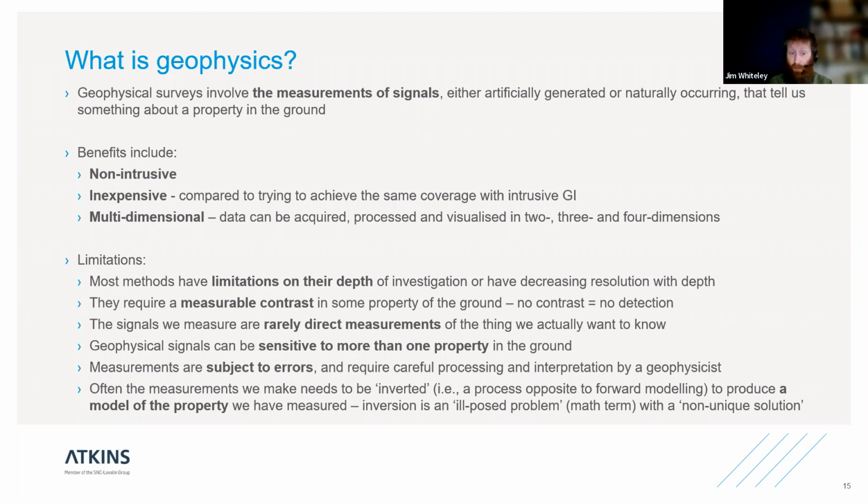And in terms of what we're actually measuring, the property that we measure using geophysics is rarely a direct measurement of the thing we actually want to know. So I've alluded that, for example, resistivity is sensitive to changes in saturation or changes in clay content, but it's not going to come back and say this is how wet your ground is, or this is how much clay there is in the ground. It will give you a relative contrast to the ground around it.